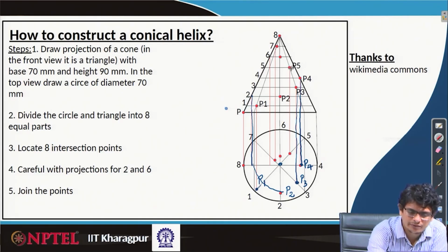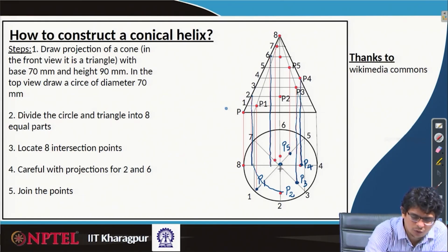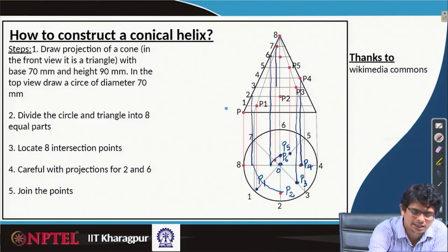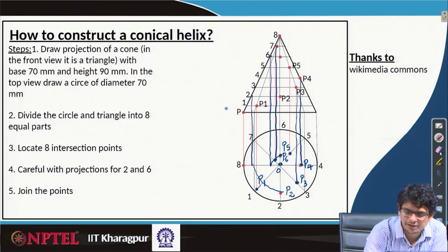Similarly, from point P5 extend it all the way down, it is going to intersect there. So call that point P5. For P6 drop a line from one of the generators all the way to N, with equal radius from O to this point make an arc, locate P6. P7 extend the line all the way down, it is going to intersect at that point.